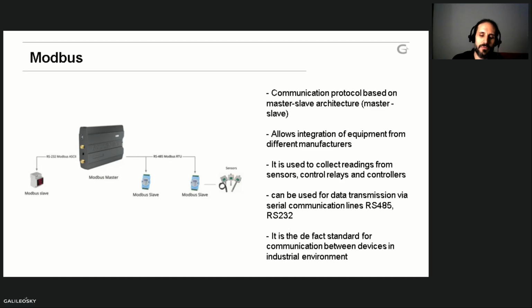Every request is formed by the slave number, the data that you want to get, which I will talk about later, the size of the data, and some CRC, and that's it, right?